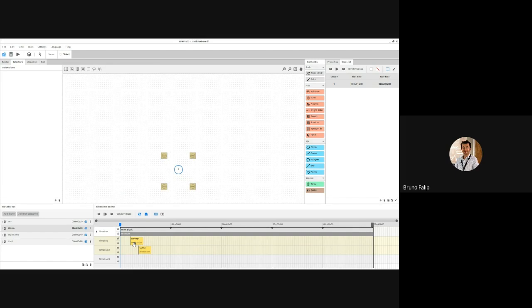The only problem with that is that most of the time we set up the DMX scenes to be looping, which is something that you shouldn't do with DALI, as it will keep sending the same command, and as you know, the DALI bus is not as fast as DMX, and this can create some delay and latency on the network.